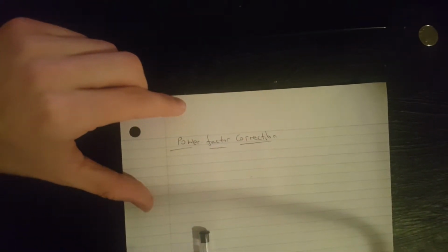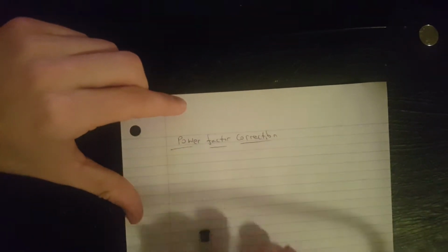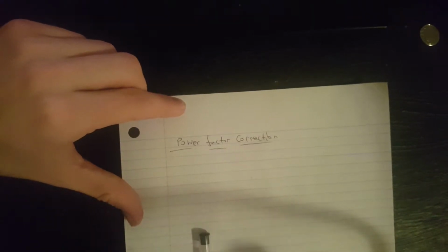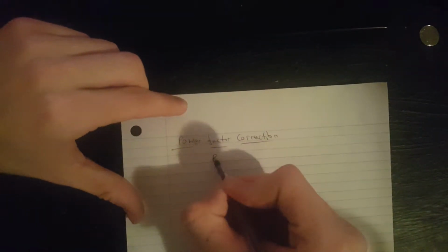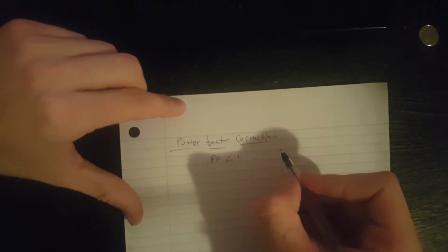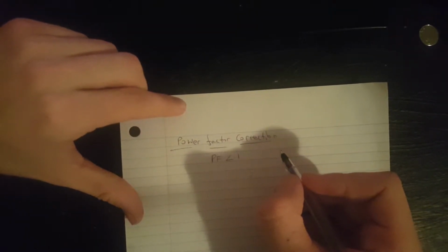So what happens is a lot of times in industry, when a power company wants to provide power to a factory, for example, and this factory has maybe an inductive load or such a thing like this, the power factor is less than 1. Yeah? If the power factor is less than 1, that means that the apparent power is more. If the apparent power is more, this is consumption of power that has no value whatsoever. But the power company must provide more current to compensate for this. And this more current costs money.